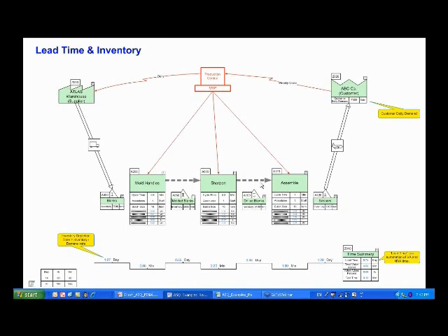So you don't want a drastic reduction, but you want to start slowly reducing that inventory, exposing those rocks and starting to attack them. It will drive that continuous improvement process. And inventory, like all the other waste, will contribute to that lead time. So as you reduce the waste, your lead time is going to get shortened. You remember I mentioned that a key outcome of a lean deployment would be process velocity and much shorter lead times.